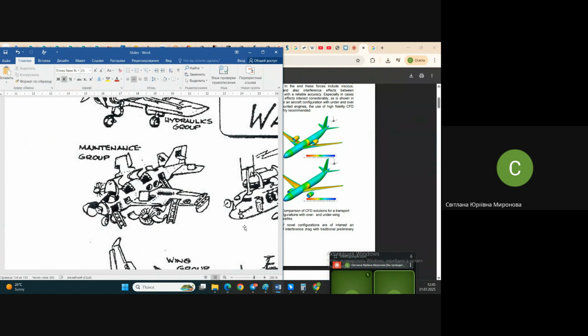They need to have access in different places of the airplane because they need to check systems of the airplane, control system, electrical system, hydraulic, and so on, all the places. Plus, they need to have access to some important places of structure in order to make sure that the structure is not subjected to corrosion, to some fatigue problems, and so on.